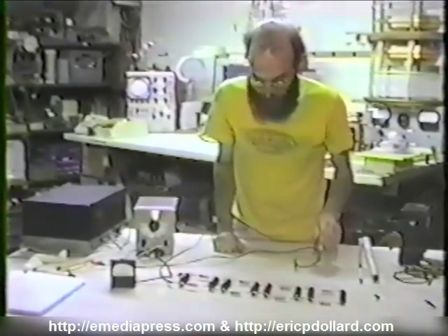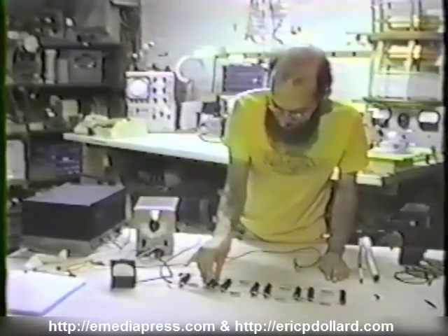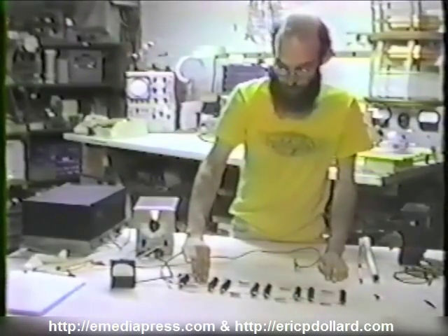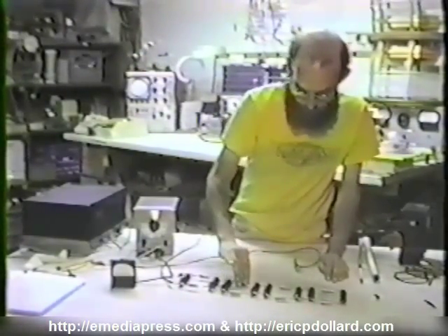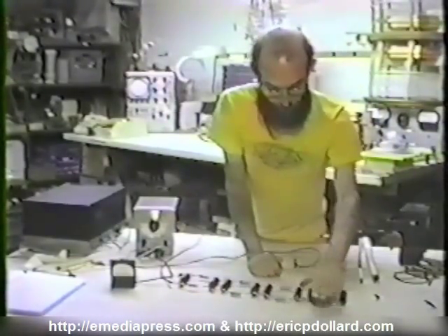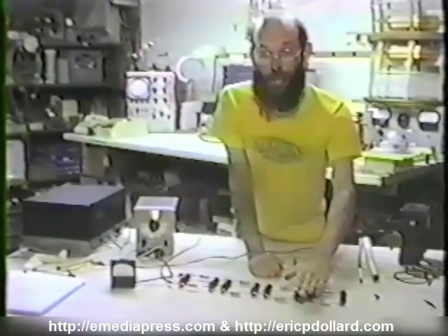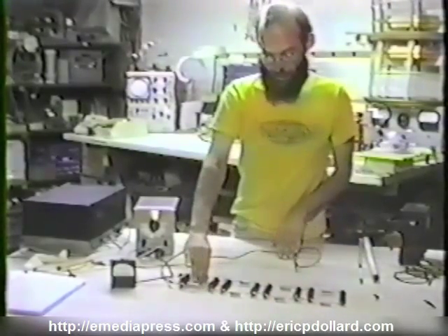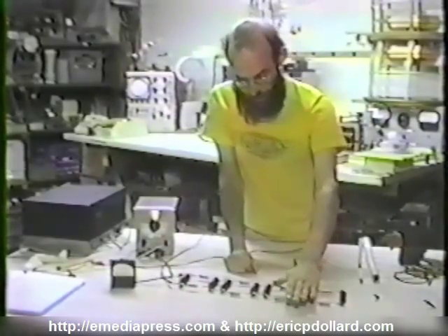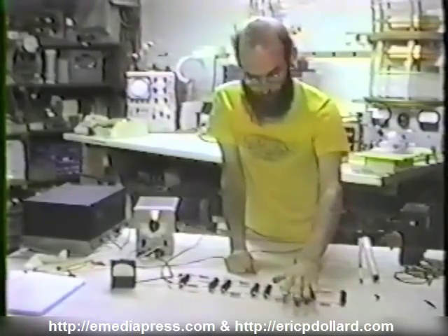And we'll do our heat check again, see where the heat's coming from in here. Feel our input coils, relatively cool. The input capacitors are quite hot. Go down the line here, capacitors are cooling off, but the coils are very, very warm, this end. So now we have the situation where the heating effect is turned around from where it was before. Now the dielectric input capacitors get hot, and the magnetic output inductors are getting warm. So we have quite a few differences here.